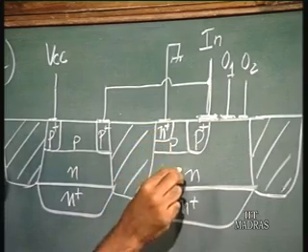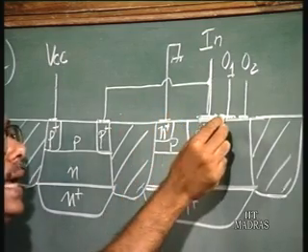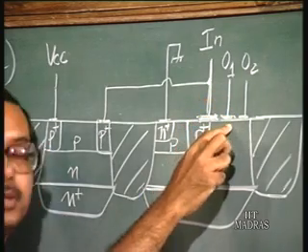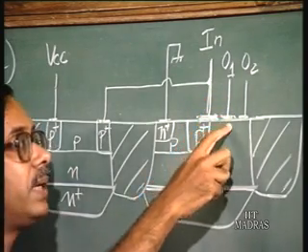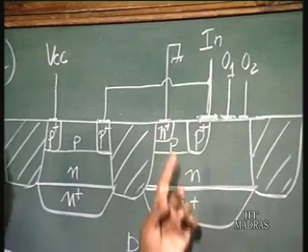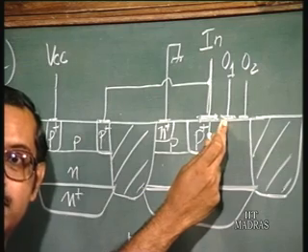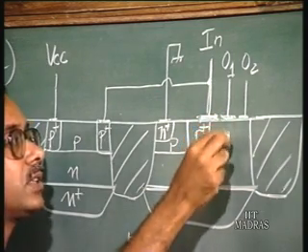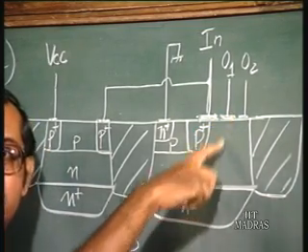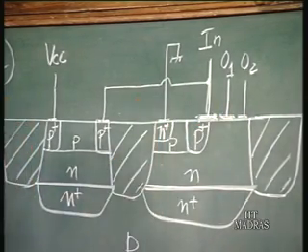So, basically this extension of the base contact over the collector makes it a Schottky transistor. This is the NPN transistor, this is the base contact, and this is the Schottky transistor. This is the collector region, and these are Schottky diodes. This metal onto the semiconductor, this particular metal which we are putting here, is one type of metal which you have for the base contact, and there is another type of metal which you are putting for the output, because this is another Schottky diode. So, this is one Schottky diode to the collector. You have multiple Schottky diodes connected to the collector, this is the N region. So, a common N region collector for the NPN transistor, and you take the outputs through Schottky diodes.